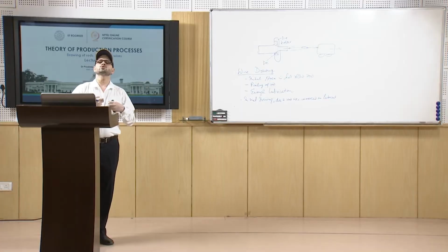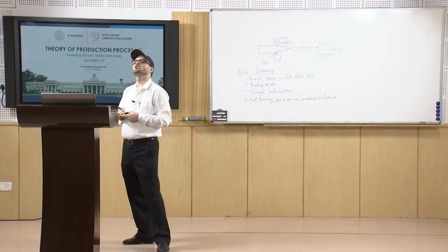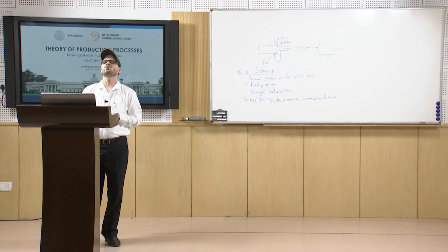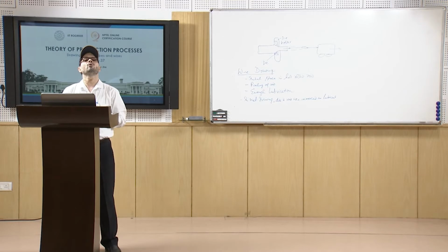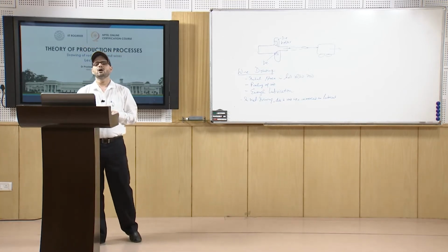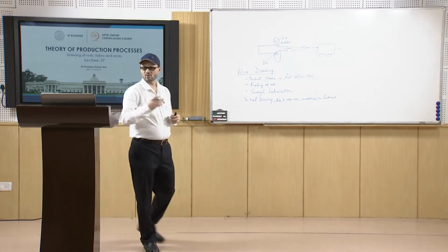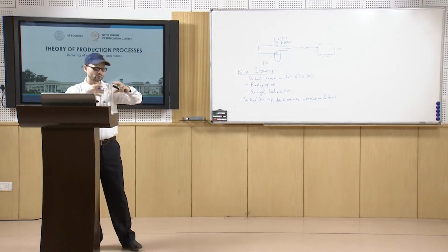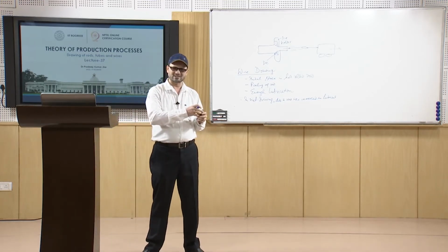Now, coming to the different materials which are drawn. If you look at non-ferrous and low carbon steel wires, they are produced in a number of tempers ranging from dead soft to full hard. So, when we talk about making wires of non-ferrous and low carbon steel, you will come across wires designated as different tempers.